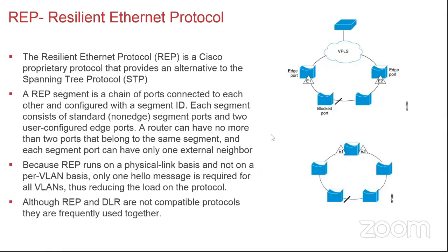One other ability to tie in multiple switches, and again, this is a Cisco-based technology that we adopt within the Stratix switches, is REP. You might hear this occasionally when doing more of a traditional ring. This is a resilient Ethernet protocol. We have the ability to tie in multiple switches either via fiber or copper. You can do 100 meg or 1 gig. The recommendation on this is not to mix speeds.